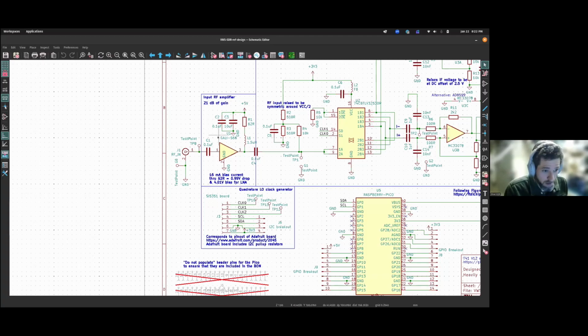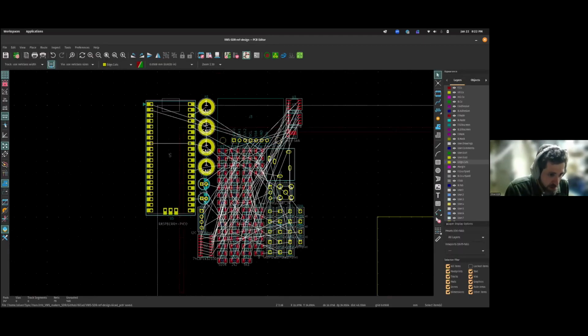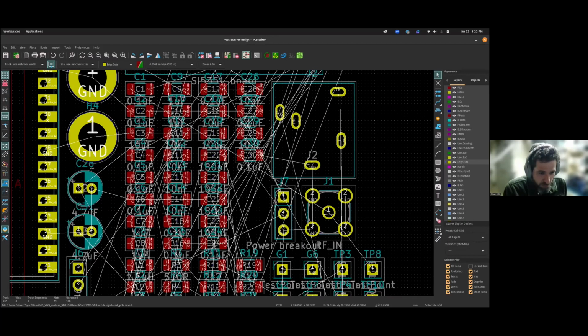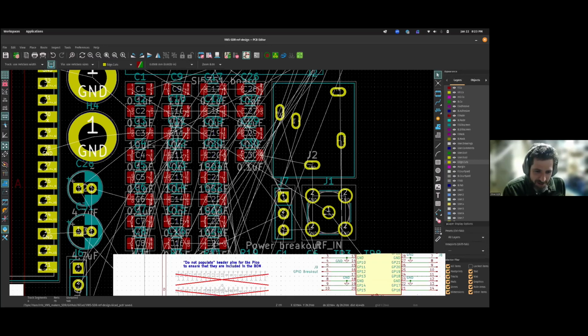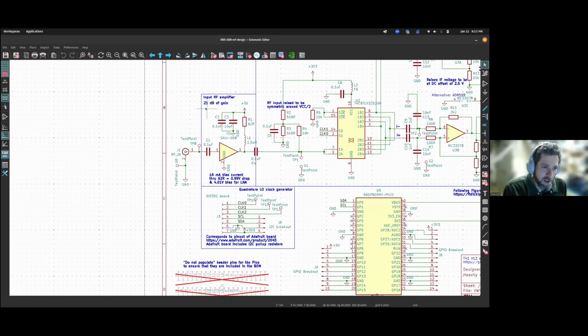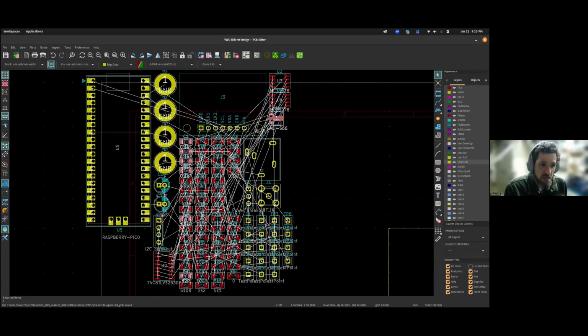The hard way to do this would be to look at the schematic and say, oh, I need to find C1 and C2 and C3, and then switch back to the PCB and scroll through and try to find them. That's what I did at first before I learned how KiCad works. So don't do what I did. The easy trick is on the schematic: if you click and drag to select a group of components, I'll deselect the test point, those symbols are all highlighted. If I now switch back to the PCB view, you'll see those same components have been selected in this tool.